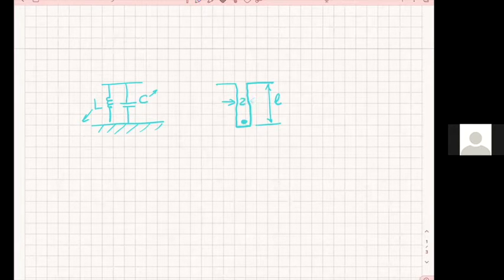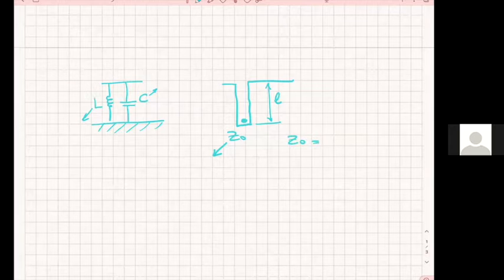I'm sorry, this is not a good visual for the characteristic impedance, so let me do this again carefully. Yes, a very small value for the length, and for the characteristic impedance also very low. So low that your width is going to become humongous. So forget it, Z naught less than 20 ohms or 15 ohms, don't do.